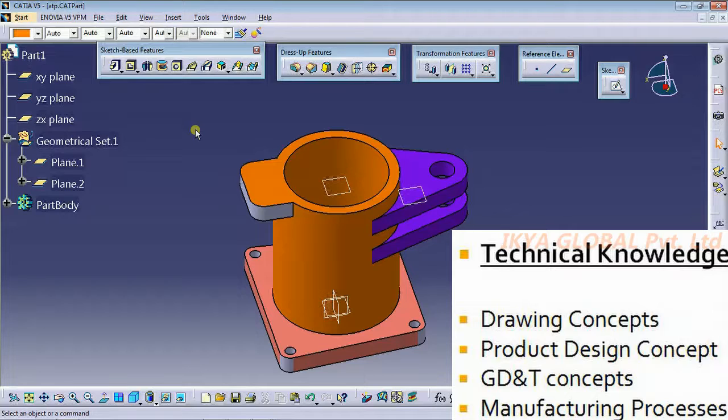Or if the component is cheap, suppose some box type where you need to place some items in the box, a soap box. For that we won't go for casting or sheet metal because its component unit cost is less. So the cheapest and best we can go for is injection molding. Apply a plastic material which is cheaper in price, then produce. So these things a designer should know.